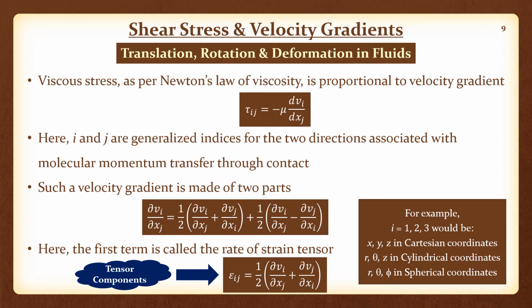So there is a velocity gradient tensor on the right hand side and a shear stress tensor, or as I want to keep hammering, because it's probably not stated enough in most books, it is the shear stress tensor, also known as the molecular momentum flux tensor, if not accounting for the pressure, right?